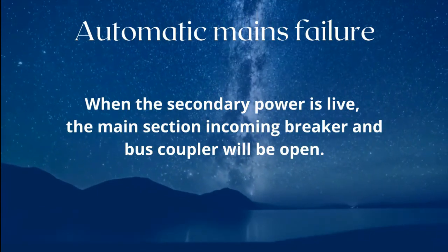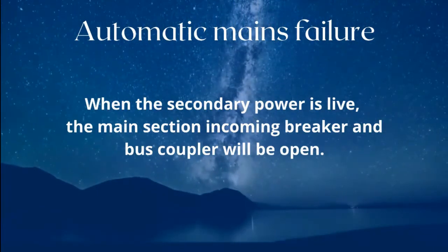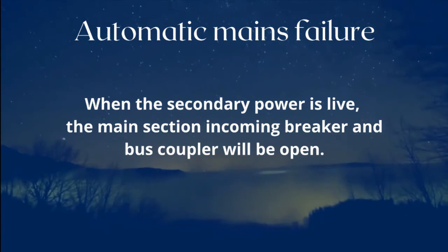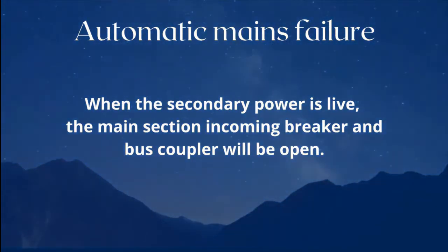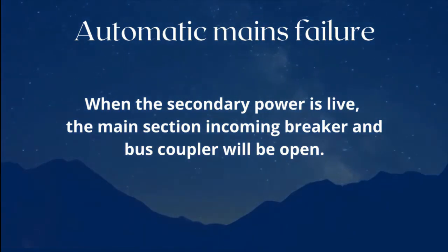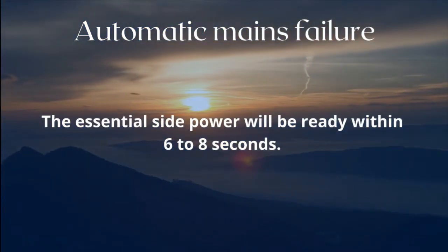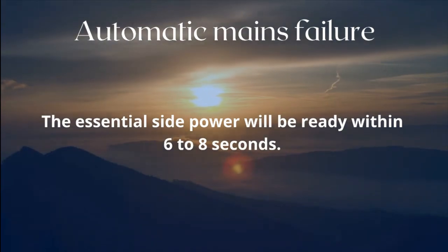When the secondary power is live, the main section incoming breaker and bus coupler will be open. The essential side power will be ready within 6 to 8 seconds.